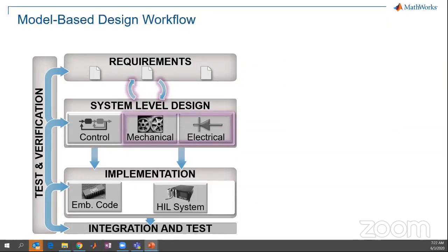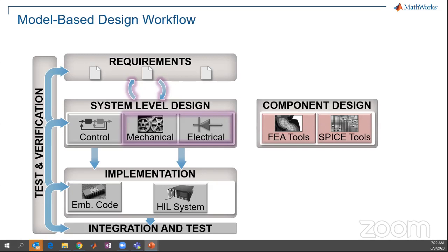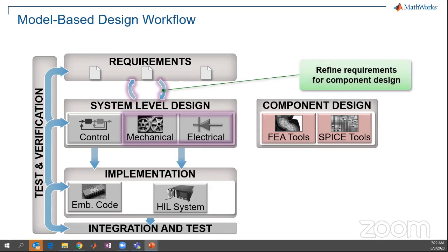So the next question you might ask: what if I already have a complete design of my electric circuit model and I don't want to redo the modeling again? Or you might ask, can I combine my existing CAD model with Simulink? Can I import my finite element analyzed machine model into Simulink? The good news is yes. We can co-simulate your original design in the simulation environment and verify your design in the entire model-based design workflow.